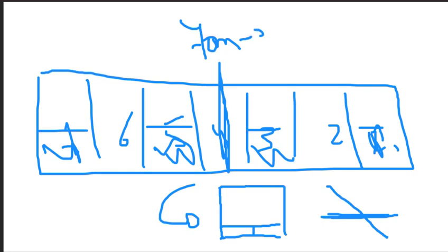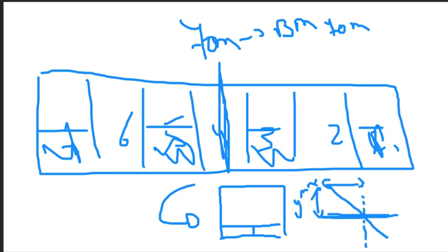First, you need to know the bending moment at 70 meters. Your stress level is highest at your weather deck, as we explained, because the distance from your neutral axis is the biggest, it is Y max.